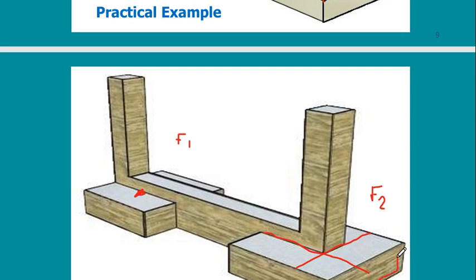It will be something like this. This is the bottom reinforcement in this direction, and this is the bottom reinforcement in the perpendicular direction. These are, of course, many bars next to each other. This one is repeated all along this depth, and this bar is repeated all along this depth. So this is my reinforcement.